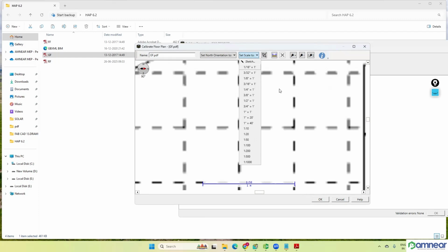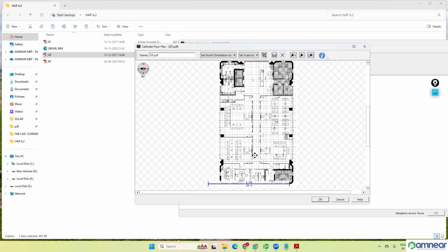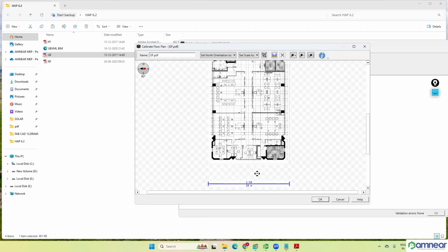In the plan sheet we have a study at the time of quantity surveying and estimation. You can go to the sketch option, you can select this one. From the starting point and end point, click first point, click the next point. It will automatically pop up a screen, a tab. There you can type the dimension, click OK. Since we are familiar, we are not doing anything here. Select it. Okay, click OK. Zoom in, zoom out, zoom select option, all those things are there. The name of this drawing, if you want to change, you can change now. Let's still keep it ground floor.